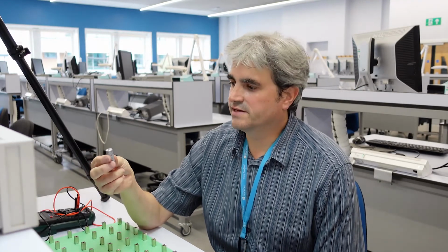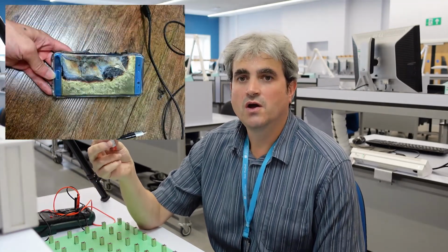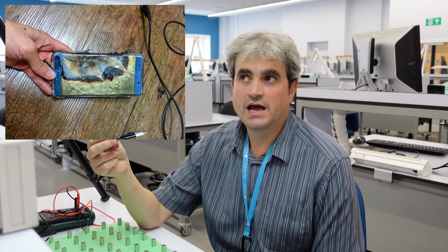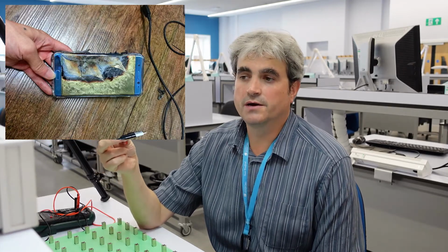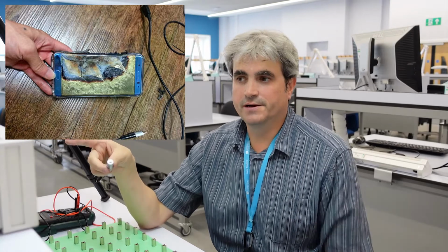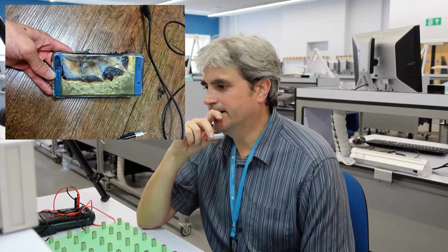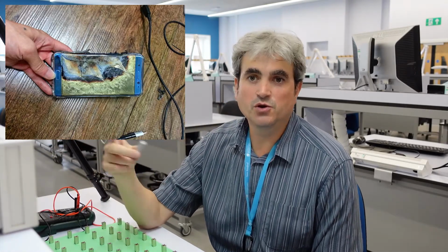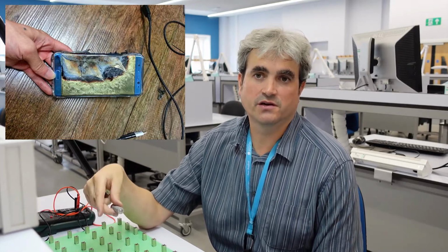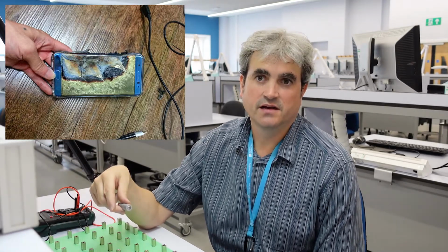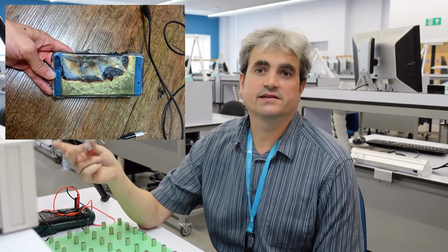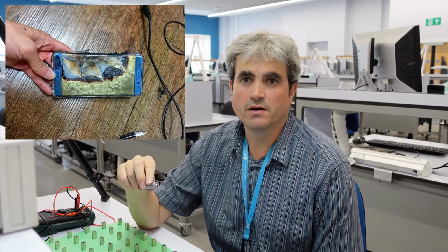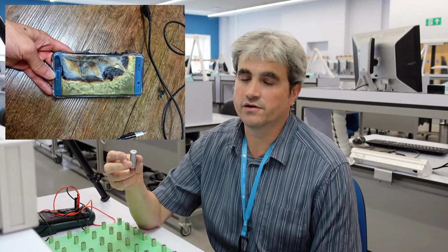So some of you may remember Samsung had a problem recently with, I think, their Note 7 device, where short circuits on the battery actually caused the battery to fail in a really bad manner. Basically, the huge amount of current that was caused by the short circuit caused the battery to overheat. It could actually catch fire and give off gases, which was why there was problems with having them on aircraft and things going forward from that.